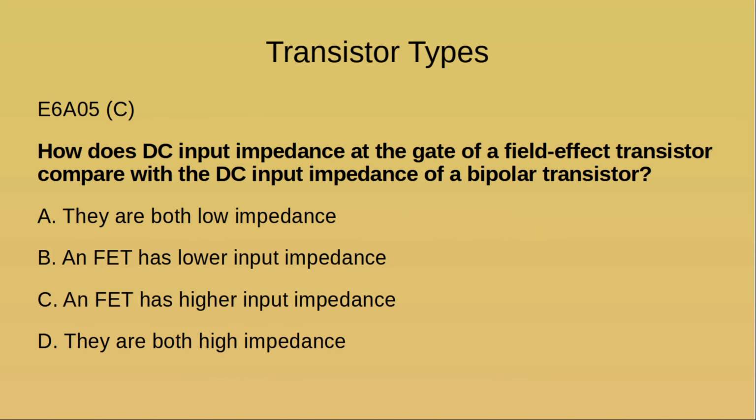So it's saying the static is going to exceed the... Well, static can be thousands of volts. Right, but that's why it's reversed, because the Zener conducts in the forward direction at the normal threshold. In fact, Zener diodes are made so it's probably less than 0.6 volts forward. But the reverse voltage is the Zener effect, and they can control the breakdown voltage, which is the reverse voltage. So you can get a 5-volt Zener or a 12-volt Zener, or all kinds of different voltage values.